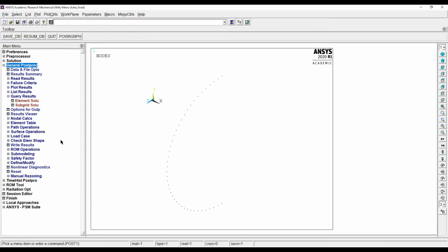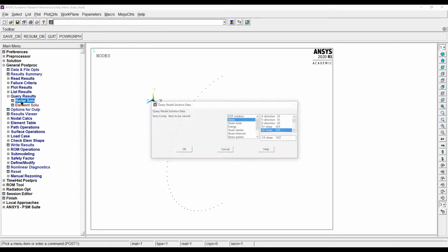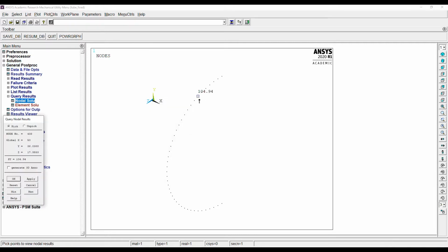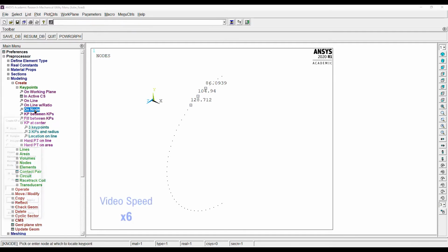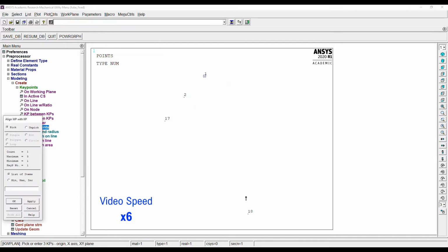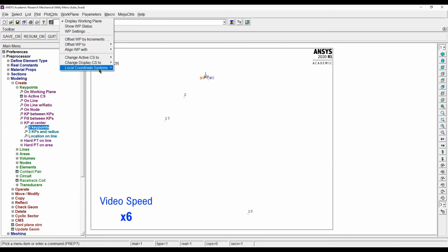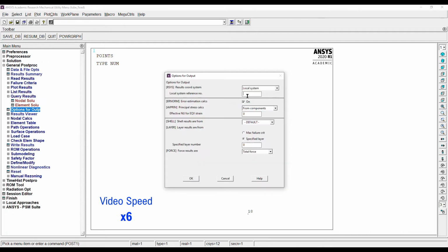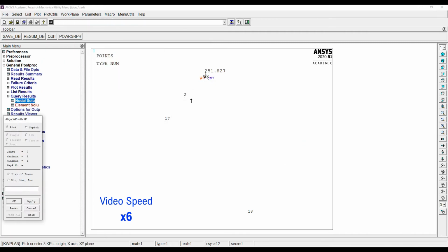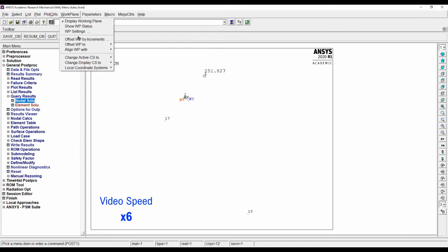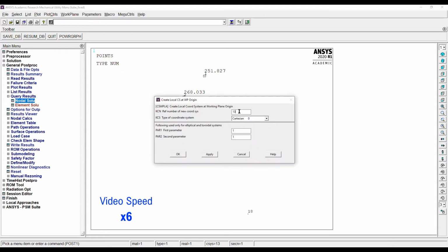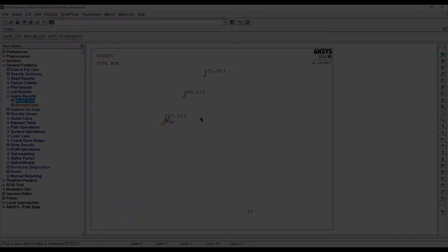Only corner nodes are required for current evaluation with tetra elements. The mid-side nodes of tetra elements have 0 stress values and must be discarded, keeping only corner nodes. After that, a local coordinate system needs to be manually defined on each node in order to calculate the proper opening normal peak stress relevant to mode 1 and the out-of-plane shear peak stress relevant to mode 3, all calculated with reference to the notch bisector line.